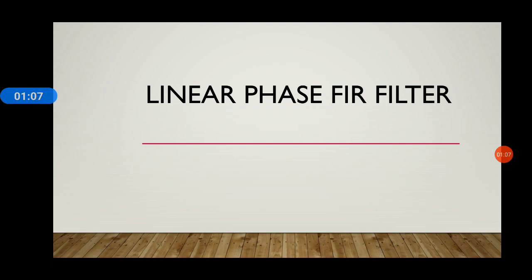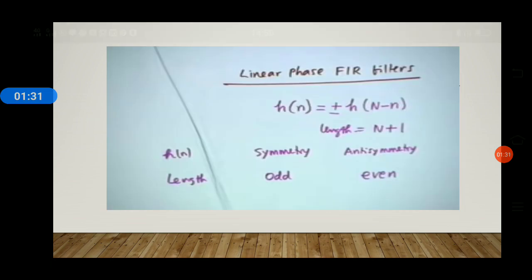As there is no distortion, it is a boon for communication engineers. And for discrete-time signals, perfect or exact linear phase is easily achieved with a finite impulse response filter by having coefficients which are symmetric or antisymmetric.